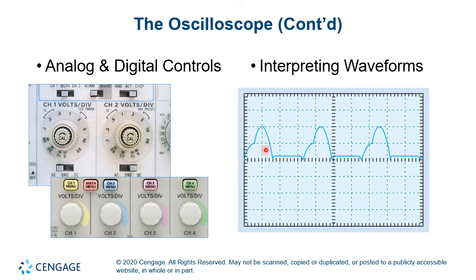So that would be thinking of DC. Specifically, this would be, I think, a DC clipped waveform. But you can measure things like frequency, the voltage, etc. Obviously, knowing the resistance, you can change that to current, and all of our other rules that we've used along the way, like Ohm's law, etc., still apply when dealing with an oscilloscope or any of these other meters.